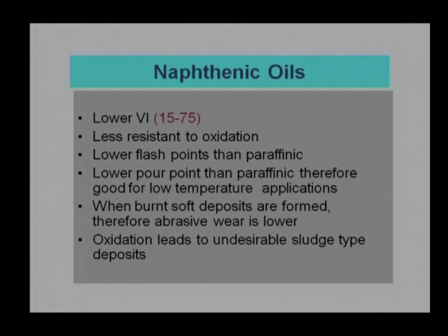So, they will have a lesser wear tendency compared to paraffinic oils, right, because of the deposits. And in addition, when there is oxidation they make sludge formation. Clearance will reduce, operating condition will change, and that is undesirable.